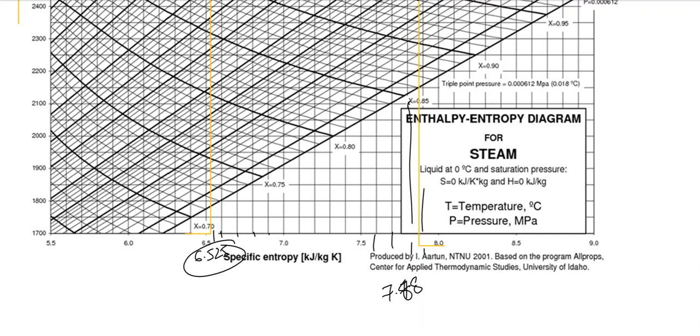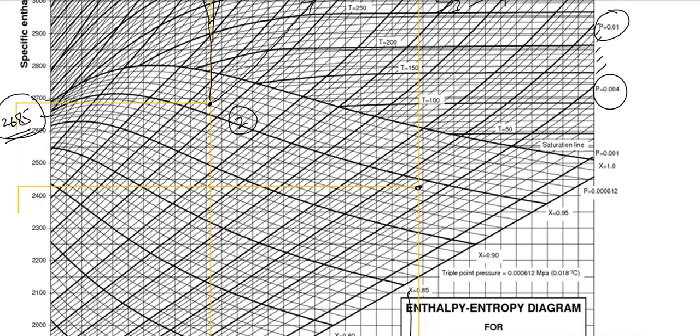That's what the entropy would be for state 3, and entropy S3 is equal to S4. So now for state 4, we can find the enthalpy. The enthalpy over here would be 2450 something. And over here, if I can imagine, 2426 something. If I just say, 2426.